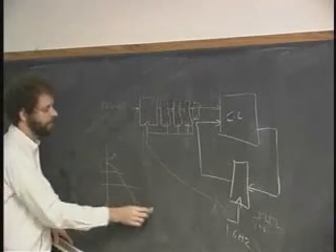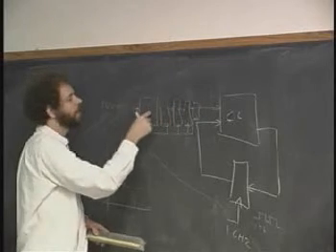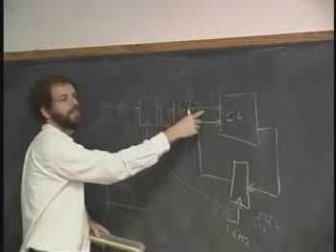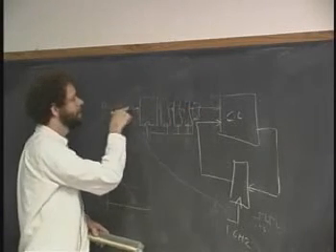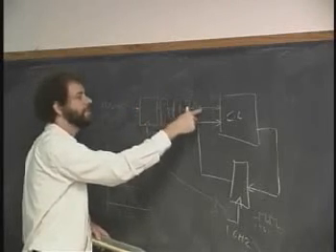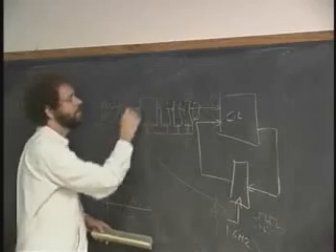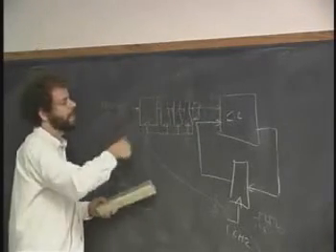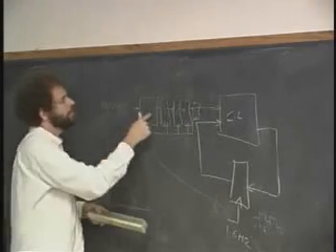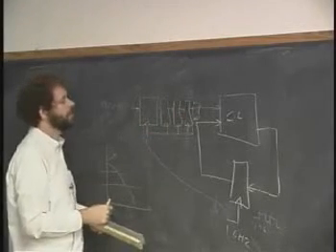Now you move it a little bit further, and by the time we get to the end of the chain here, we've had 100 clicks to do it, or 100 billionths of a second delay between the input and the output here, and the probability that it is still somewhere in the middle is extremely low. And so I can build myself a pipeline of flip-flops like that and basically hand off the task to the next flip-flop in the assembly line to get the job done. That's one way to do it.